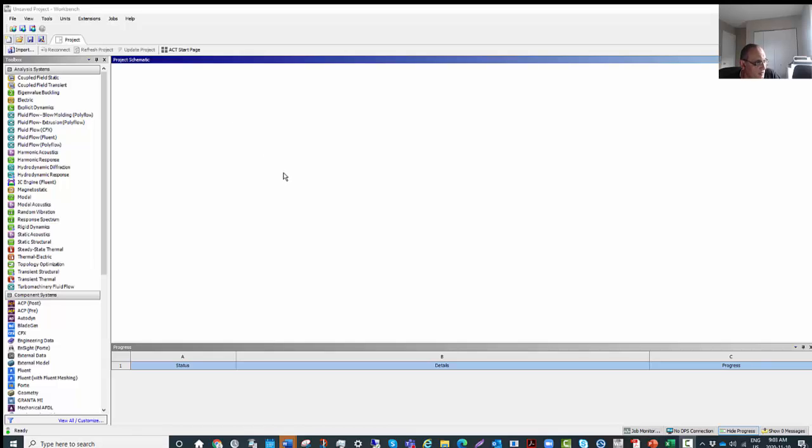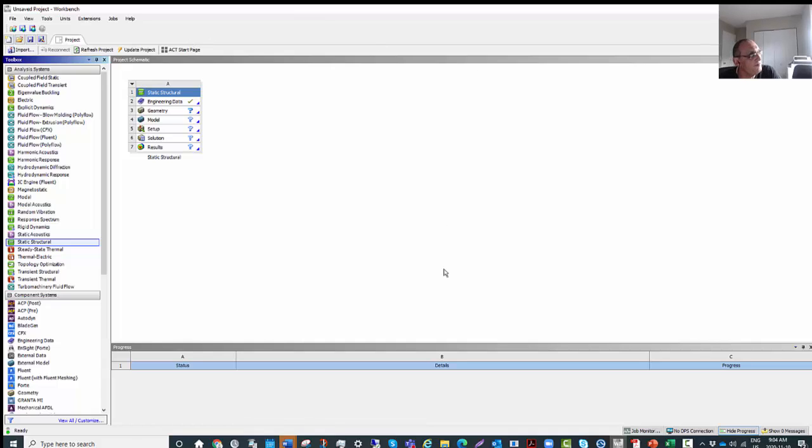Good morning, everyone. So I thought to register a second lecture, or a second Ansys example, again, to show you how to use the Workbench. And again, we are doing structural analysis. So if you double click on structural analysis, or simply you can just take it and move it into this workspace here after you start Ansys, of course. And then you can, of course, name it.